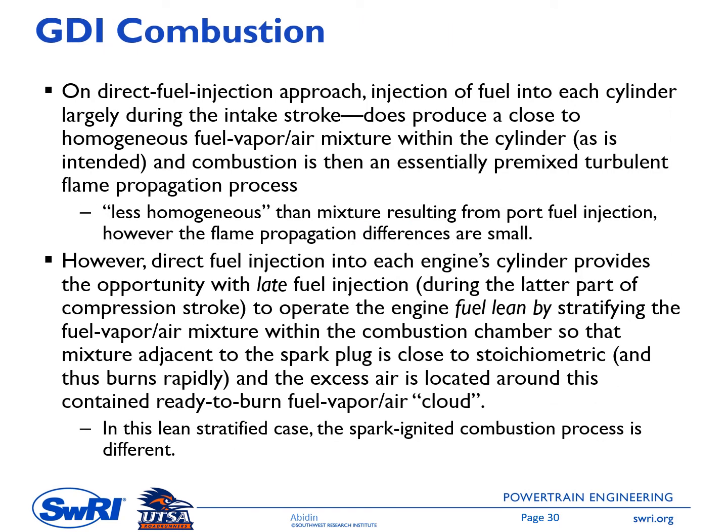For GDI, the fuel is directly injected into the cylinder. We inject the fuel during the intake stroke if we want a more homogeneous mixture. We can also inject the fuel during the compression stroke if we want a stratified mixture. In this case, we have a stoichiometric mixture around the spark plug and a lean mixture far from the spark plug. Compared to PFI, GDI will have a less homogeneous mixture, so we might have different flame propagation between GDI and PFI.